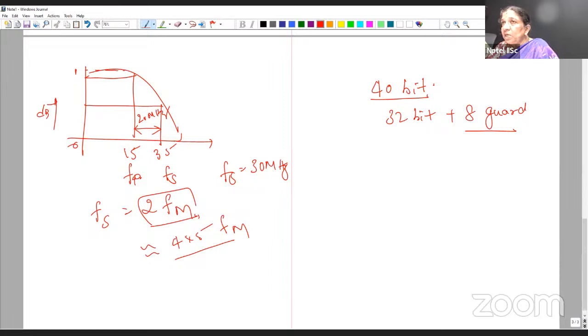Although I'll be using two registers, the registers are 32-bit each, but we combine them: only 8 bits of one register and 32 bits from the other register, what we call a register pair. We use it to do 40-bit addition. More than that is not possible; it has to be scaled down to that.